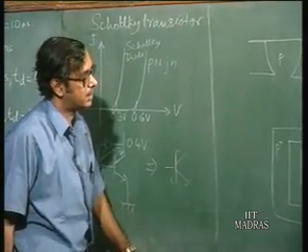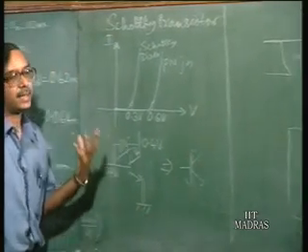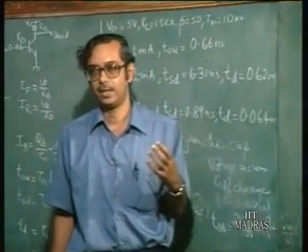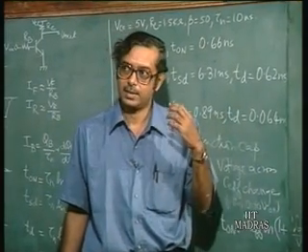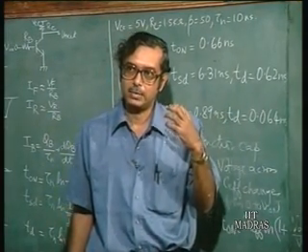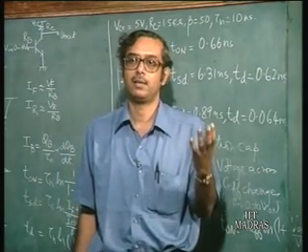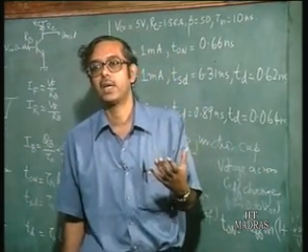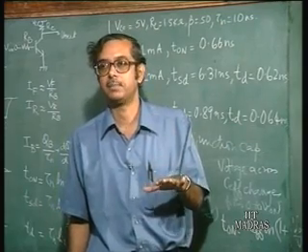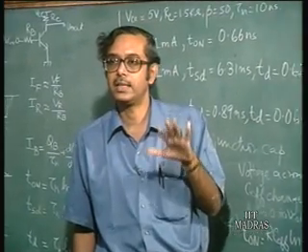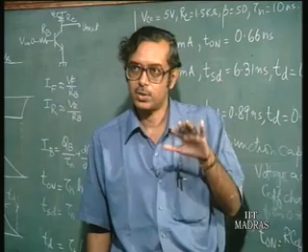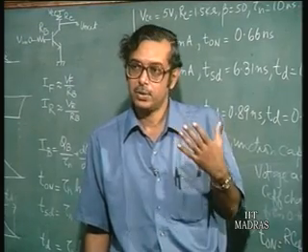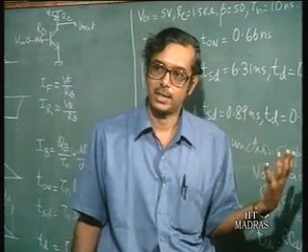So, you see that in a digital circuit, to improve the maximum operating speed of the circuit, you have to reduce the storage delay time, and to do that what you can do is you can have a Schottky transistor.